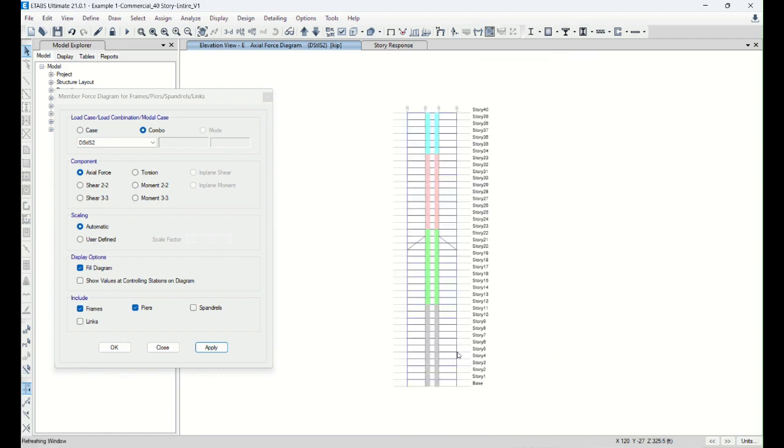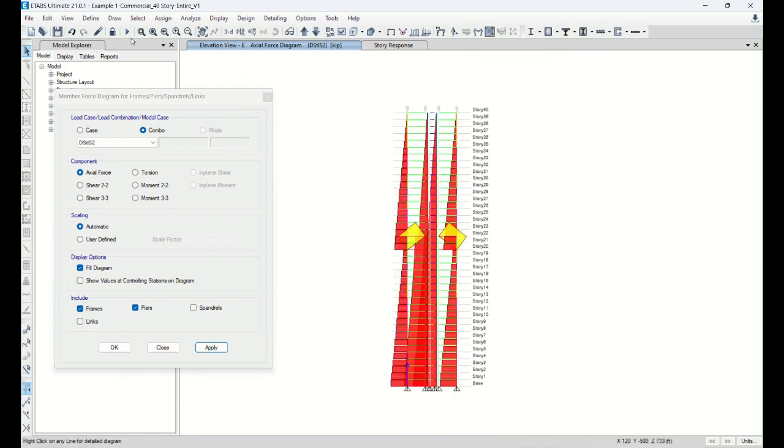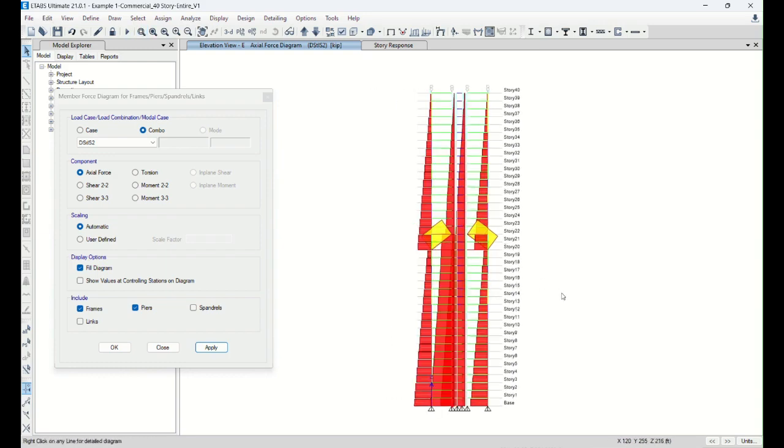Likely you're gonna underestimate your gravity forces on your column side, column design. Previously, you designed the column based upon only gravity loads, but now since you tie the column with the core wall with outrigger, these two columns, and the other side, it's not only a gravity column. This also works as a lateral column because it's contributing.